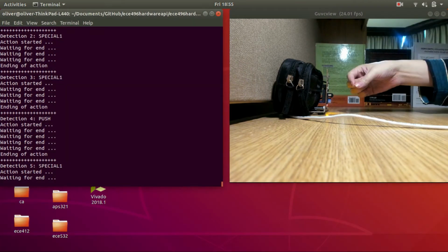The final one is a special gesture we support. It is defined within the near range of the radar. We see that the accuracy of the motion is pretty good, but the number of generated data points may not be large enough for the machine learning model to predict the result. This is because the duration of the motion is relatively shorter. This motion also needs to be right in front of the antenna on board to ensure good accuracy.